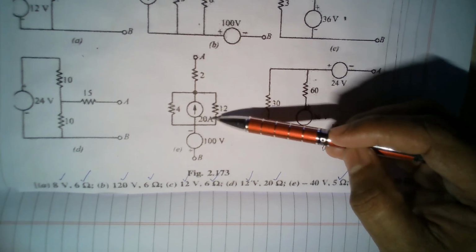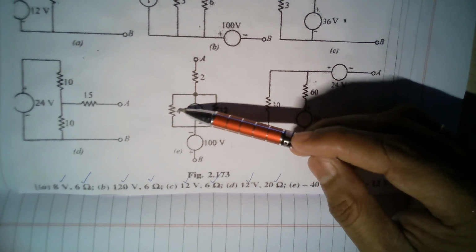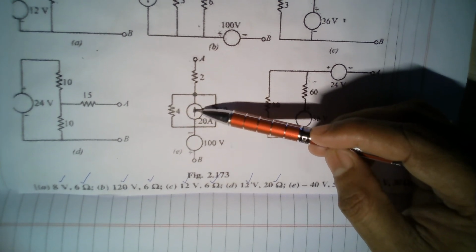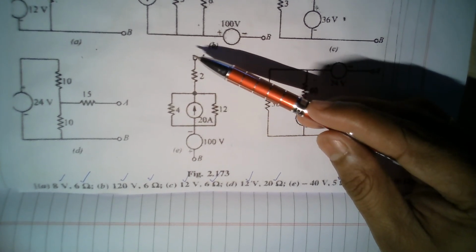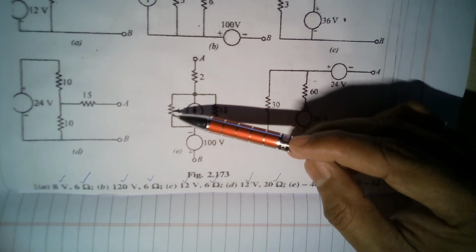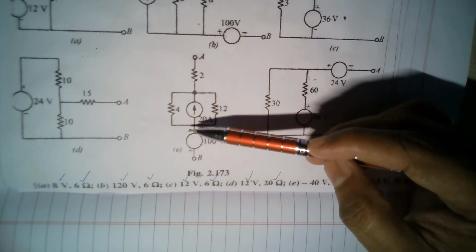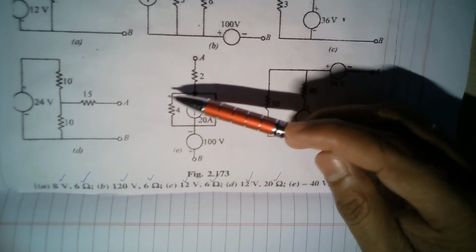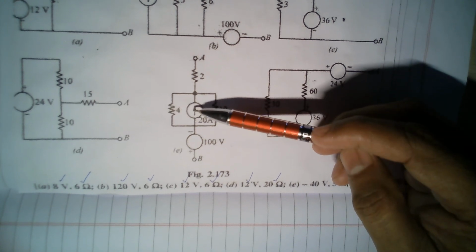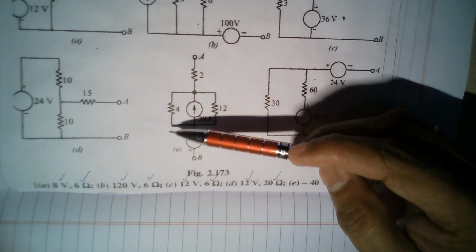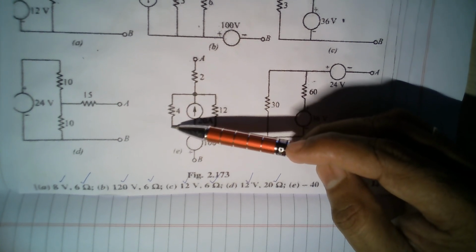So simply forget this 12 and make this 4 into 3. That's it. It will be same. Now 20 amperes go up and it cannot go into A because it is open circuit. So 20 amperes will go left into that imaginary 3 ohms resistance and again comes back. So 3 into 20 will be 60 volts of voltage drop. But here the current goes up and then this side the current coming down. Okay, so this is high potential and this is low potential.